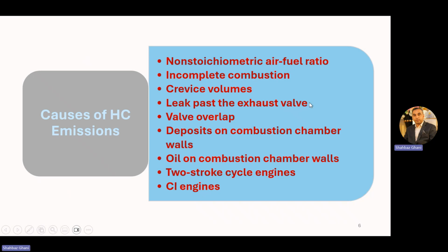Then, leak past the exhaust valve. During the exhaust, the temperature and pressure are quite high, and some of the gases might leak past the exhaust valve, adding to the hydrocarbon emissions. Valve overlap timing means both the inlet and exhaust valves are open for 15 to 50 degrees of crankshaft rotation. During that overlap, some flow goes into the exhaust and some flow goes into the inlet, so the overlap is also one of the causes of hydrocarbon emissions.